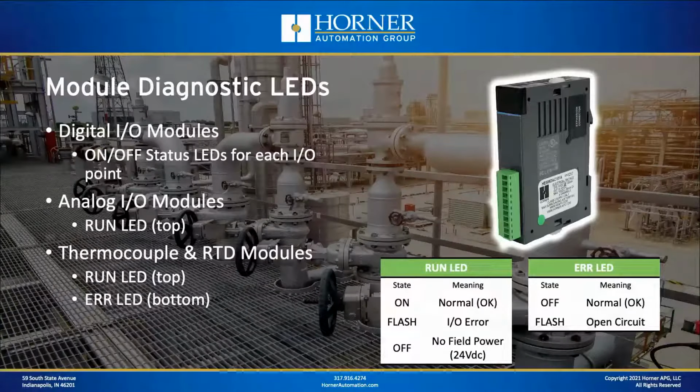So if you have a thermocouple sensor connected to a channel and it's open circuit, which means it's damaged and probably needs to be replaced or fixed, typically replaced, then you're going to get a flashing light on your module as the second LED down from the top through the window, indicating that you have that error condition. And you have one LED for all 4 channels. So if any of the channels has an open circuit, you're going to get that LED to flash. That's why it's important that you disable any channels you're not using, because they more than likely are going to be open, not wired to anything, and you don't want any kind of false error indication.